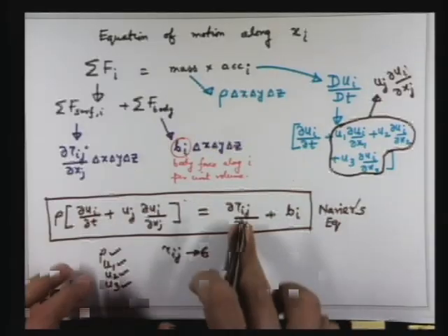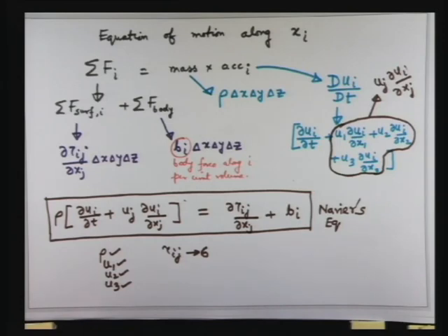So that response to an input is in terms of stress strain behavior. Now for fluid, it is not important to relate stress with strain. Rather, it is important to relate stress with rate of strain or rate of deformation. This was emphasized very emphatically in our introductory lecture by Professor Som, that you require for fluids stress to be related to rate of deformation. So our objective will be to relate tau ij with the rate of deformation.